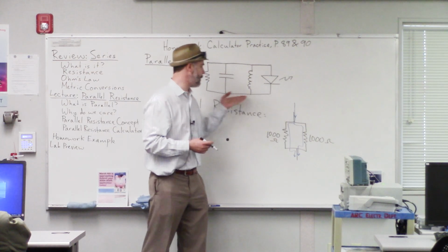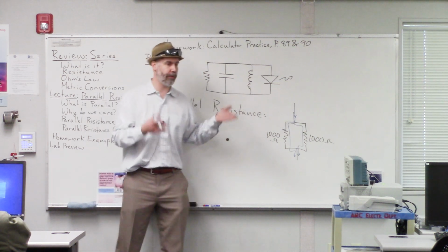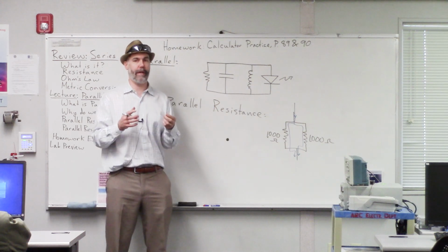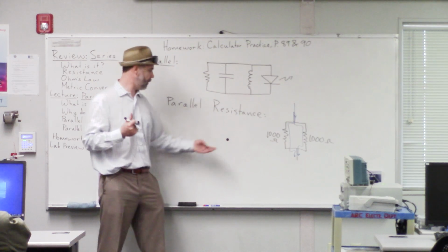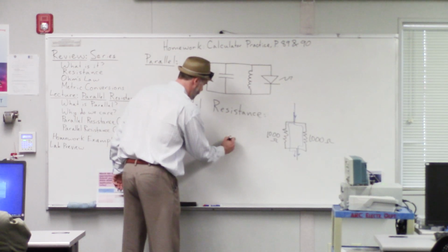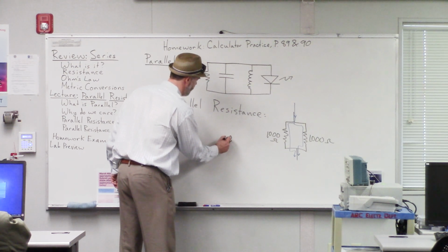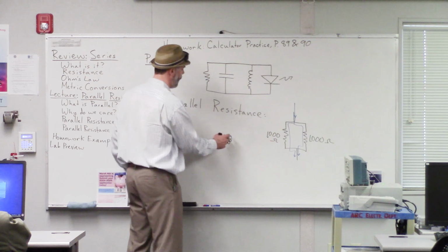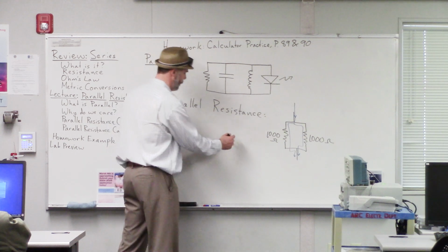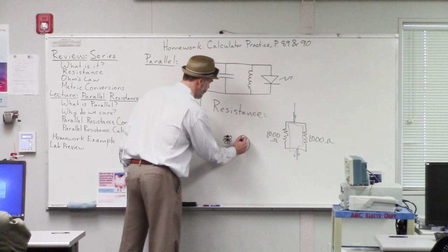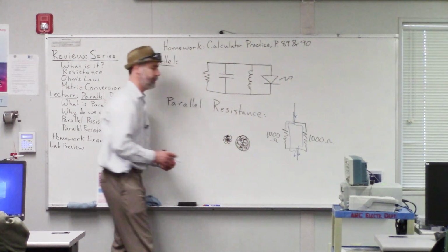When we're doing problems up here on the board, we treat wires like they have 0 resistance. And that's a good approximation, but in the real world, nothing is perfect, and even wires have their own resistance. So yeah, a narrow wire like this will have some resistance, and the more cables or the more filaments, strands of wire you put around that, the less resistance you'll have altogether. Or just the bigger you make that, yeah, the less resistance you'll have altogether. So yeah, that's a good point. Thank you.